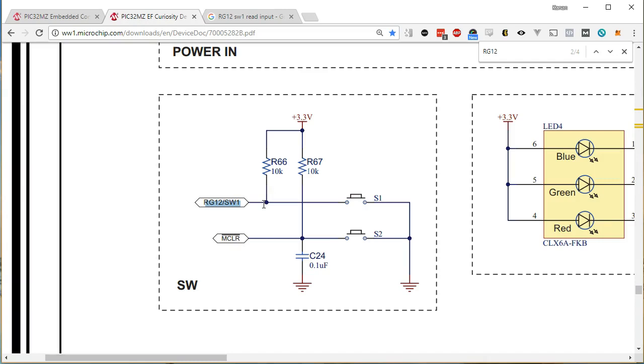And static can come from anywhere. It's one of the enemies of these chips. Literally just walking across some carpet and you touch the chip, you're at 4,000 volts or whatever from static electricity. Even though the amperage is very low, the current is very low, these wires, this stuff is very, very tiny, and it's enough to burn out.